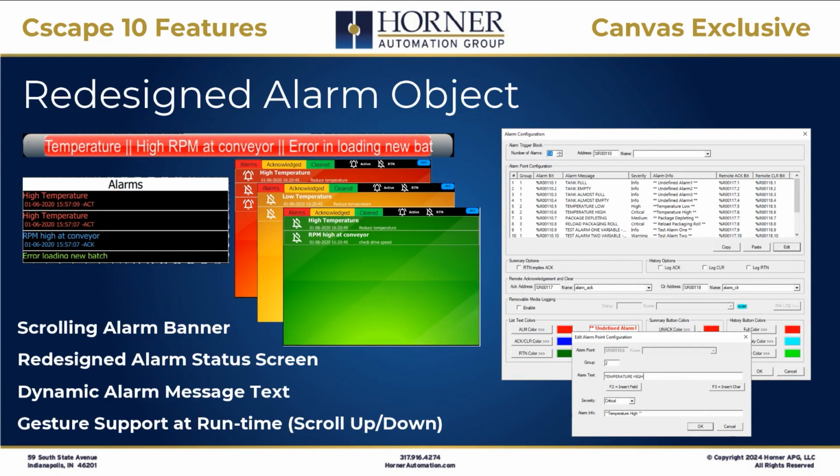From an alarm standpoint, you have a lot more tools in Cscape 10 for displaying alarms and annunciating alarms. So you now have an alarm banner that will only display if you have an active alarm. And then it will scroll across the screen with an alarm message if it has multiple alarms or the alarm message is too long to be displayed at one time on the top of the screen.